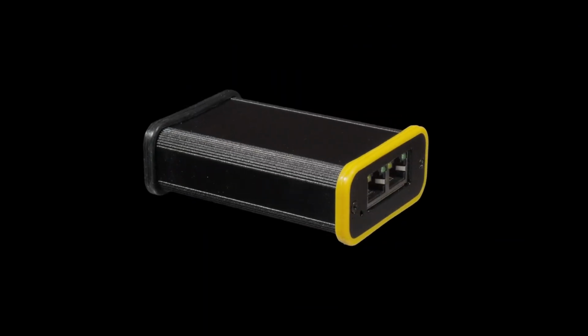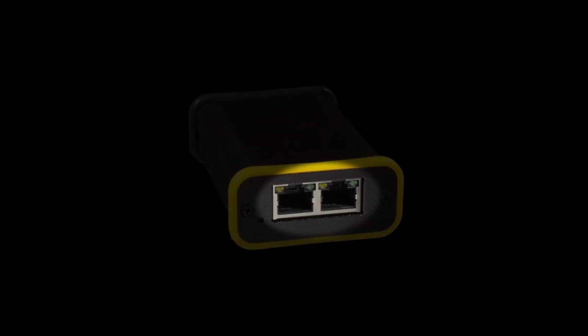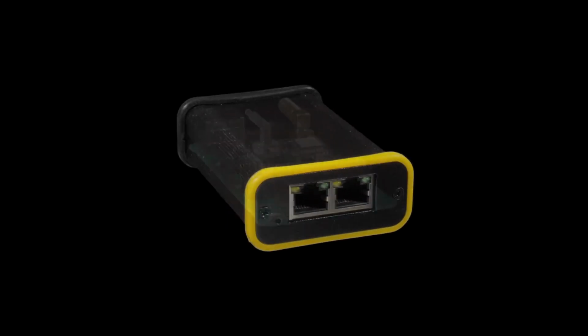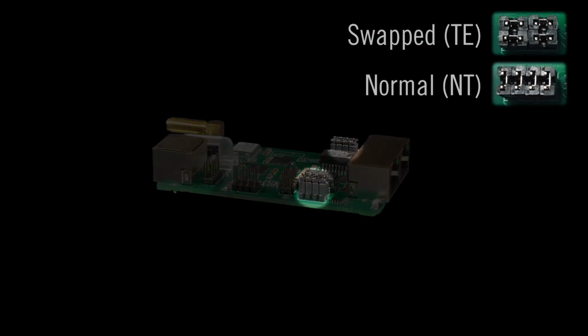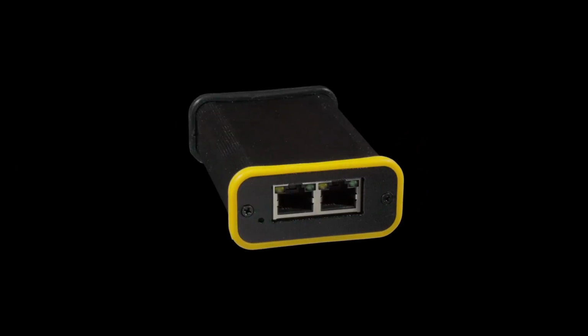Okay, let's get started by getting more familiar with the device itself. On one side, you find the two E1 interfaces using the classic E1 pinout, same as the DFU cards for instance. Some internal jumper blocks can be changed to swap RX and TX pairs to support NT roles if you're using straight cables for instance. But I'd only use that if really necessary, because opening the device, or rather closing it, can be a bit of a pain, especially aligning the light pipe with its matching hole in the front panel. Trust me, after assembling the whole first batch, I'd definitely recommend against it.